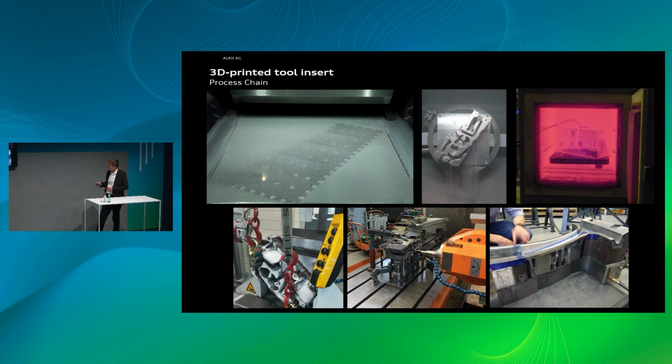And then it's a question of depowdering. Also, Bernd Weimann has mentioned this earlier in his speech. So the depowdering of the cooling channels is very important. And the second step behind that, you need, of course, a specially designed machine, and we have an optimized serial machine there, because a tool segment and the build platform weigh something around 150 kilograms. So you need a special machine there also.